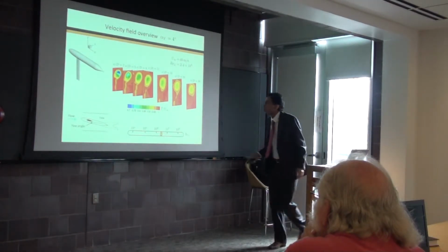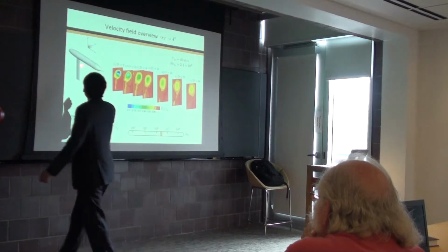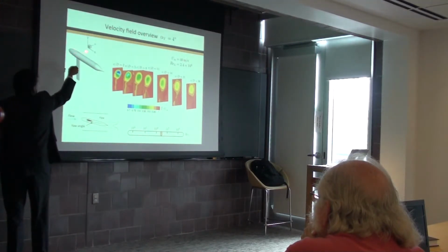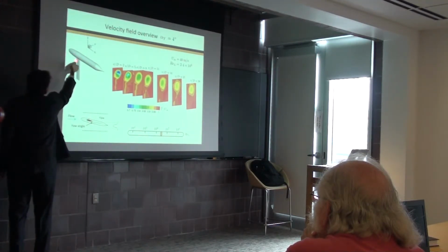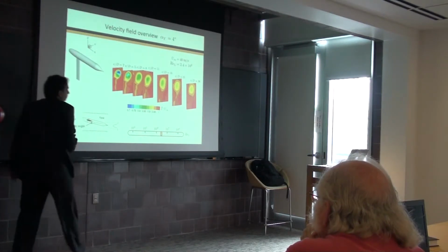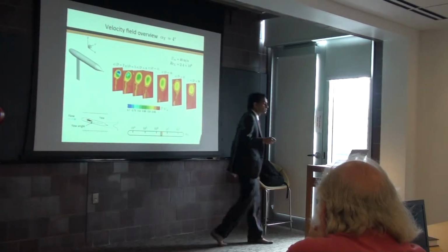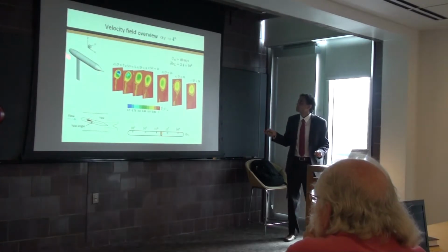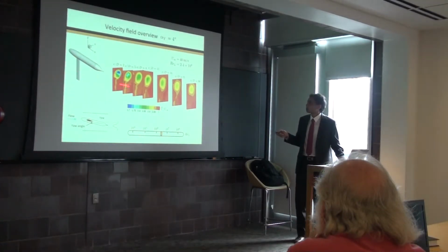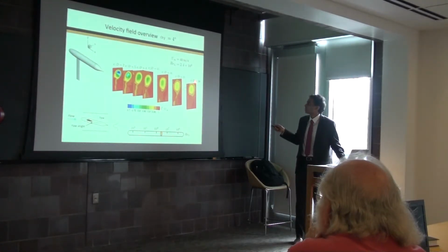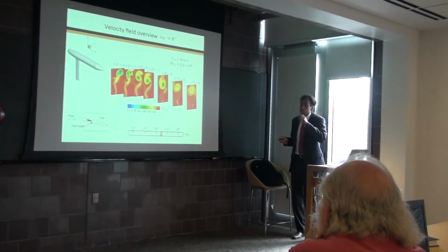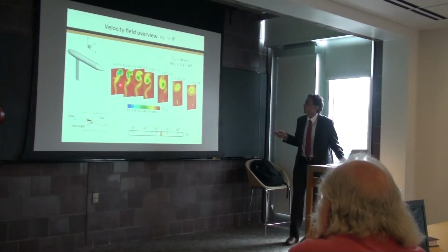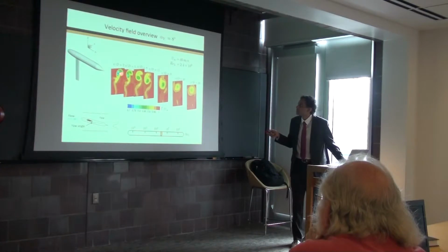So what's happening here? Well, in pitch, the separation was happening on the left and the right of the body. In yaw, it will happen on the bottom and top. Of course, we've seen in the previous flow visualization that the separation from the bottom was affected by the support, and that's shown here. It's interesting to note that by the time you get to the final downstream location, you only seem to see a footprint of a single vortex. What's going on here? Well, if we increase the angle from 4 to 8, we can see that a little more clearly. We see the footprint of a weaker vortex and a stronger one.